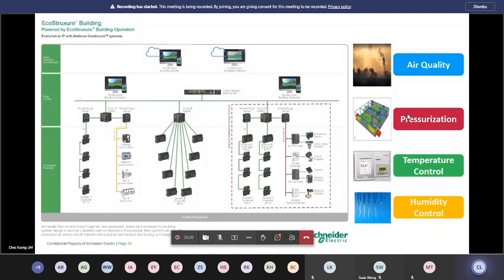If we were to fall back on the traditional MSTP kind of connection, the speed, reliability, and resiliency of the system is not that great compared to IP, because in IP we definitely know there's a big bandwidth. We can send across huge amounts of data that is very much needed within a controlled environment, especially critical control. So in our Schneider Electric BMS, we have a freely configurable IP-based system, which is technically as flexible as an IT system that you can provide.